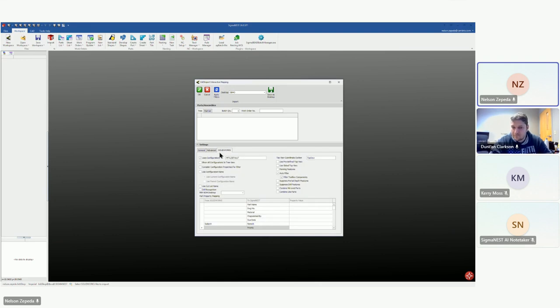And then back to that SolidWorks tab. So I already mentioned the property fields, but you have your configurations at the top if there's a specific configuration we have to pull from, and then the auto filtering that I've mentioned. In this case, I turned it on, and it should run the parts through our feature recognition, because we also have some tube software, so it'll try to recognize if there's two parts in there and pull those out, and then also toolbox components. And like I said, it's not perfect, but it's better than nothing.